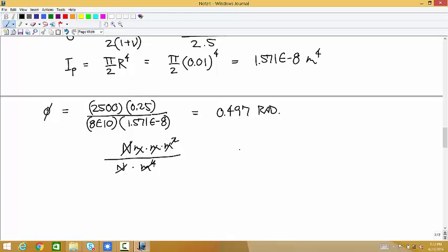28 degrees. Okay, 28 degrees, that's a lot. You might not want to do that to a steel bar and count on it much after. But that's how the calculation goes. Okay, so that's positive, so that twist is coming this way, in the positive x direction.